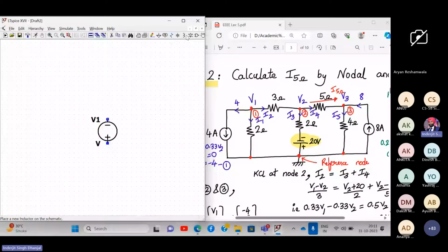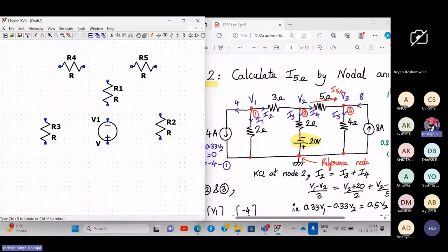Now, do you see this nearby? If you go left hand side, 1, 2, 3, 4 components, you have a resistor. Click on that, and in order to place it, tap it once. So it's placed. If we want to place more, keep on tapping. I require one over here, one over here. In order to rotate, press Ctrl R. I've rotated it, now I tap once. Don't tap it double, or else the numbering will be affected. Then press escape. So R1, R2, R3, R4, R5 automatically came. Do you want me to repeat or is this fine?